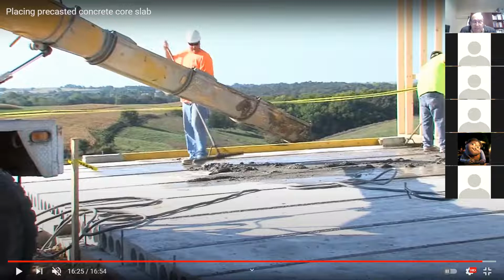The PT slab that I'm telling you about is in any house, especially in Irvine. The reason we use it is because there is a soil called expansive soil. I don't know if you have heard about expansive soil before. Expansive soil is a type of clay that senses moisture. Once you add water to it, it enlarges in size and pushes whatever is above it. It can bring the entire house up.